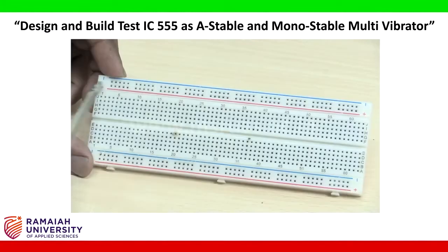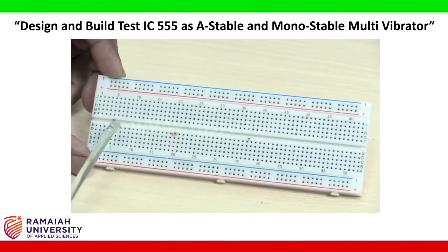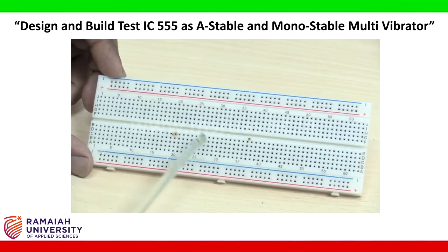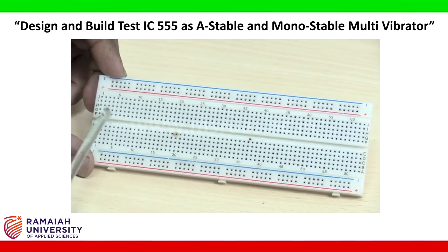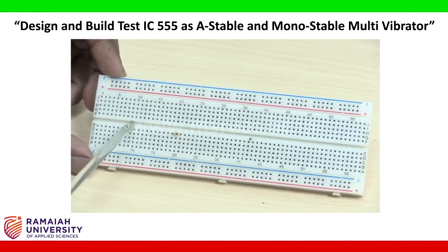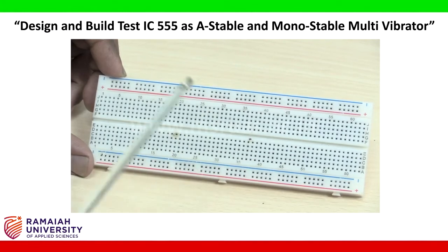Circuit board. This is the circuit board or breadboard. This is used to connect our entire circuit. This is the series connection till this large gap, and again this is the series connection. This is the series connection in x-axis and this is the series connection in y-axis. Till this division, which will be counted to 5, it is a series connection. After that this is one connection.